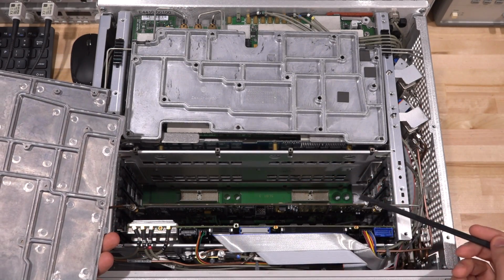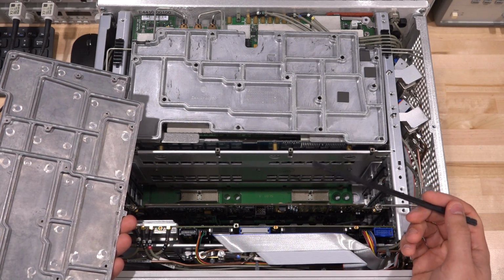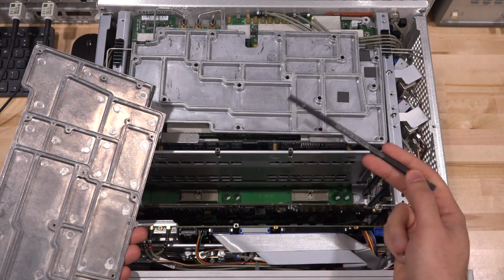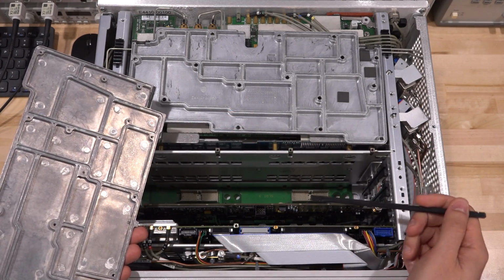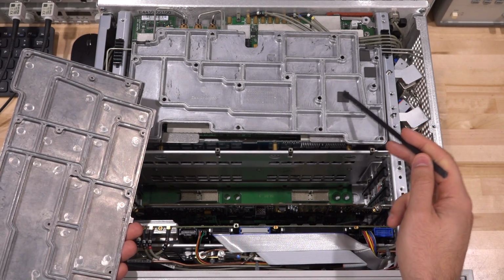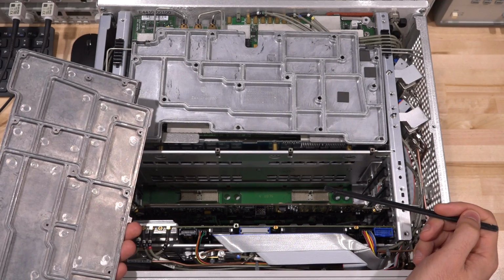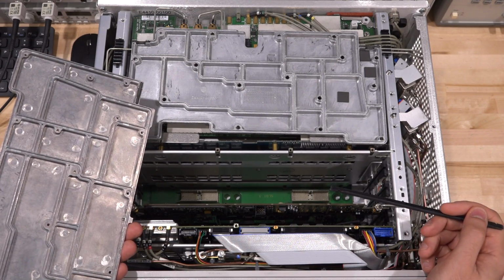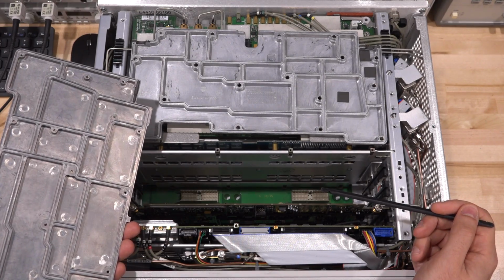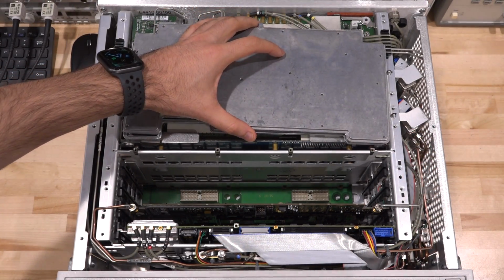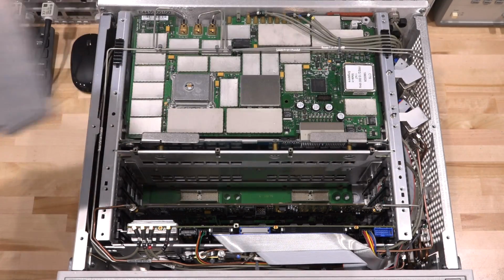Now you would never want to run these without the enclosure during normal operation, because not only are things not isolated as they should be, but some of the effect of these ground planes on the walls is taken into account in the design of all the microwave interconnect. So you definitely want that. And you can also see RF absorbers here built into the chassis to eliminate some kind of a resonance or cavity from forming, and reflections bouncing back around inside the individual compartments here. So I've already taken this apart, so I'm going to put this aside. But we're going to do this test anyway.